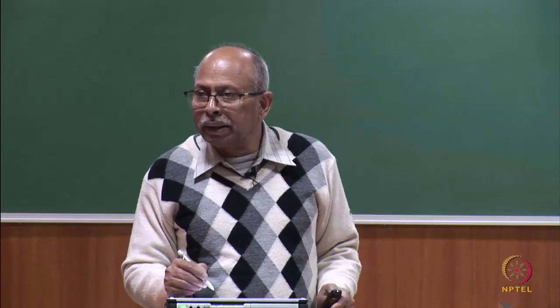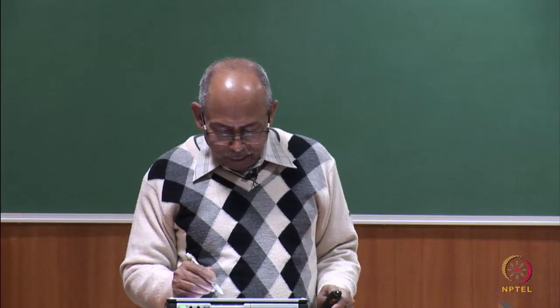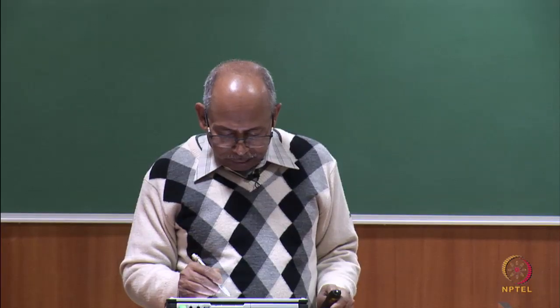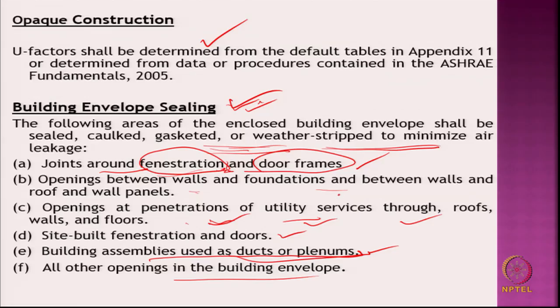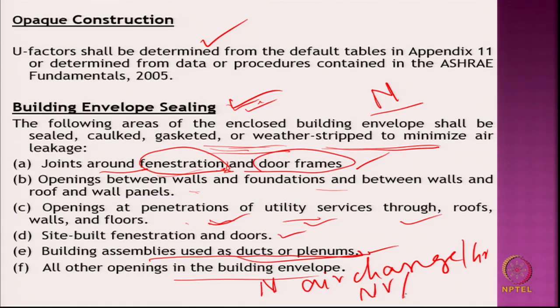Remember, I talked about air exchange rate sometime. I might have mentioned what it is. Air exchange rate, air changes: the number of air changes per hour, that is the total airflow in 1 hour, n times multiplied by the volume. N air changes per hour means that n times the volume of the room per hour will be the flow.